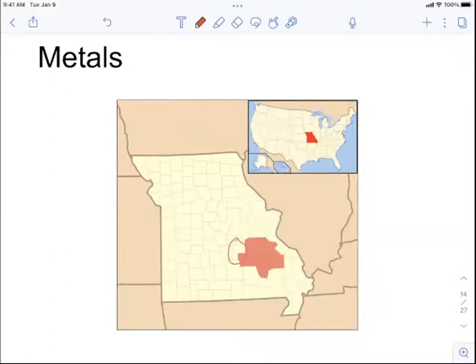What we want to prevent is these metals getting leached into the groundwater or river water, because it's quite difficult to remove them, especially the heavy metals. If it's ferric ions or those hardness ions, we can remove them through the softening process. But if it's heavy metals, then it's going to get pretty difficult to remove them.